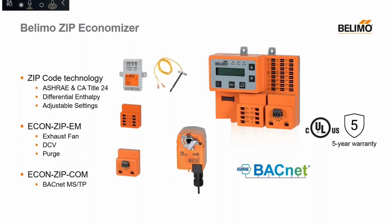The energy module, the module plugged in the middle port of the Econ Zip base, will be really beneficial. It has an exhaust fan function, a DCV mode that you can select that 800 to 1000 ppm range, and a purge function. The COM module, the module plugged in on the right port of the Zip base, is where we have BACnet MSTP technology.